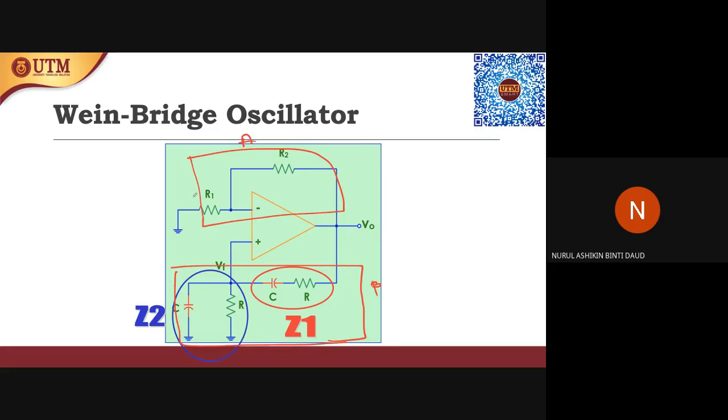So how to calculate the gain A? Let's first calculate the amplified gain, which is A. If you recall what we have learned from op amp, there is a current flow here, let's say I2, and there is also current flowing into the inverting part, I minus. I1 plus I2 would equal I minus.